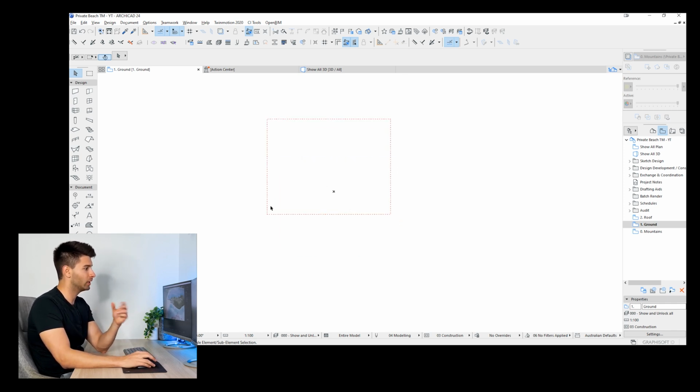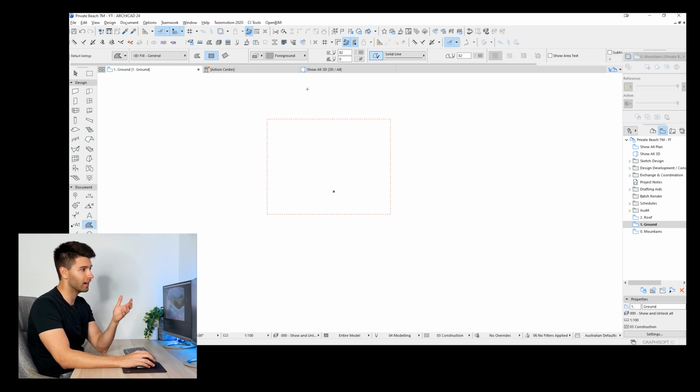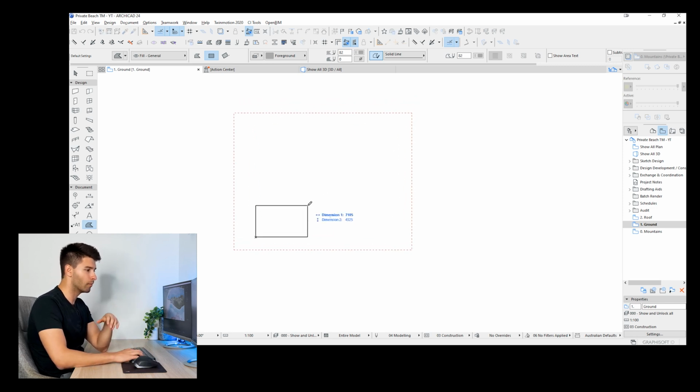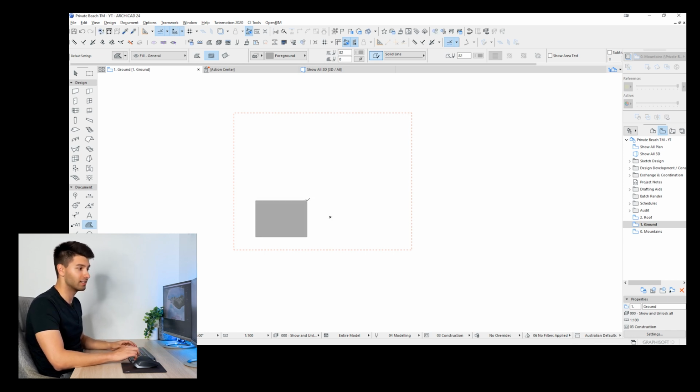So the base of this building is going to be the living spaces, and I usually start by creating just some generic squares to understand size, proportion, and things like that. So if we were to design a living room and a dining room, we'd probably give that living room 7 meters by anywhere from 5 meters to 7 meters again, because we're going for that nice elongated design, in my opinion, on this one. We want another dining room to match it, so another 5 meters by 5 meters is more than sufficient. That is a very giant dining room, and you can easily cut that in half if you're restricted by space. However, in this instance, we're definitely not restricted in any way, shape, or form.